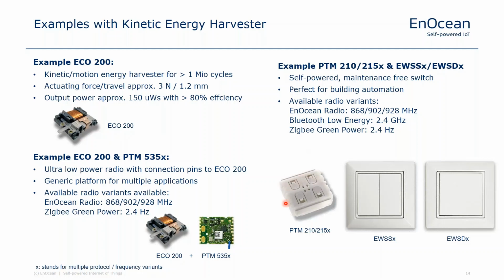This is the module. You can click it into different frame sizes or frame designs. It's fully maintenance-free, battery-free, and perfect for building automation and available for all frequency ranges. De facto, it's available for even more, like the Friends of Hue system is also supported. It's a variant of Zigbee, but it's fully supported. Also available as a finished device, then called EWSS or EWSD, switch housing design.